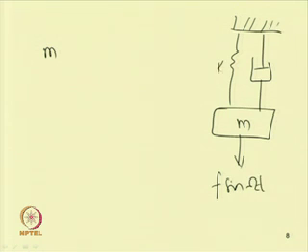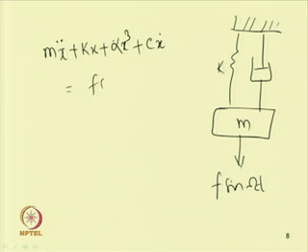So, in this equation, this is the inertia force, then the spring force I will keep nonlinear, that is k x, the linear spring force, plus alpha x cube. So, this is the cubic nonlinearity, plus I can add the damping C x dot, equal to F sin omega t. So, in this case we can always take the scaling parameter and the bookkeeping parameter in such a way that the coefficient of the response x for the nonlinear term and for this damping term will be of one order lower than that of the linear system.